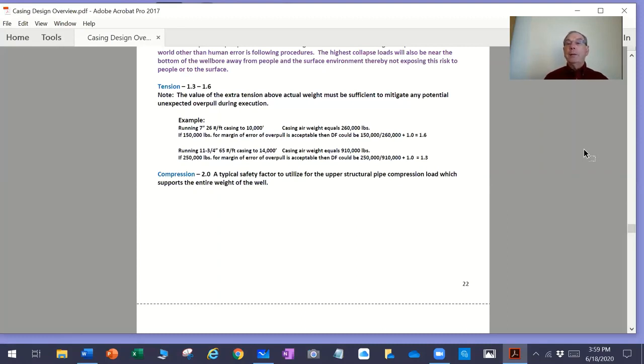for that particular type of casing string. So it's going to be based on your operating area, and most of the time different operating areas would choose values based on experience somewhere between 1.3 and 1.6. They may use 1.6 for the upper casing strings, and then when you get to the deeper, long intermediate casing strings, they may use a number less than 1.6. It's still going to be safe.